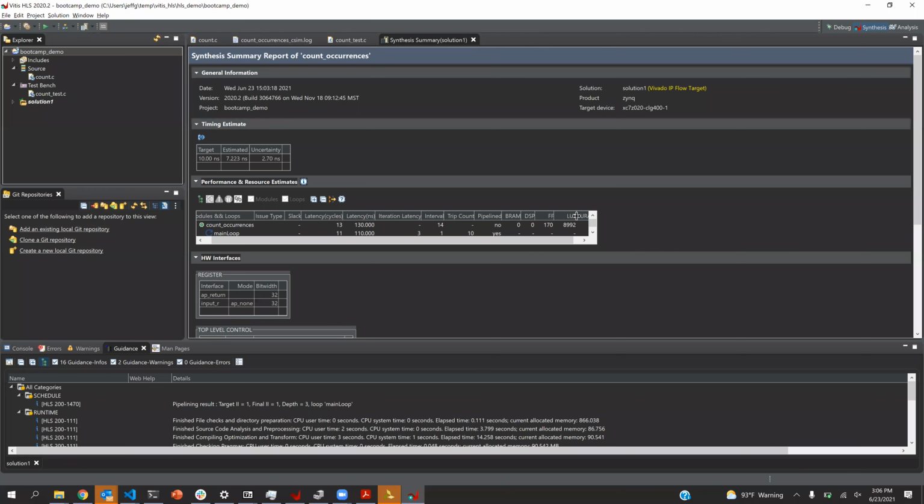Do those tools generate caching logic and stuff like that, or do you have to put that in your code? Okay, caching logic, you'll notice we're going to quickly run out of space. I can make this huge looking array with 1,000 entries, but that's not that much. Real big data would have perhaps millions or megabytes, and we don't have much VRAM space. So what we would really like is to store data in the gigabytes of DRAM we have in main memory. It's slower to retrieve and fetch, and we need to do it through a bus. We're going to do that in a second here.